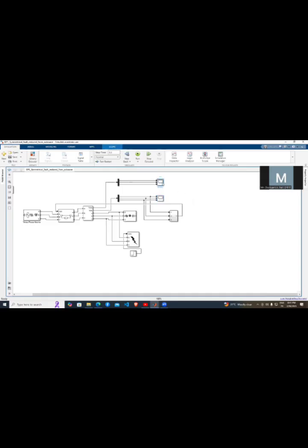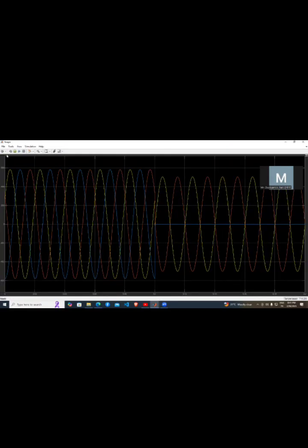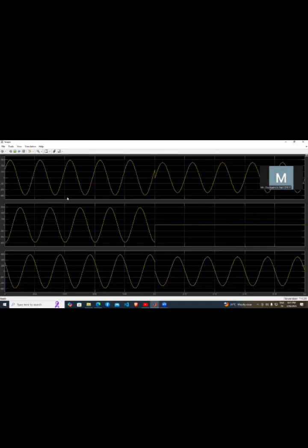Similarly, you can check the voltage. Now it is line to line fault. See, these are the waveforms. If you want to see on the single phase, then click on these three icons, that is layout, and make this a 3 output. Then you can check this output as a 3. If you want to take the printout.